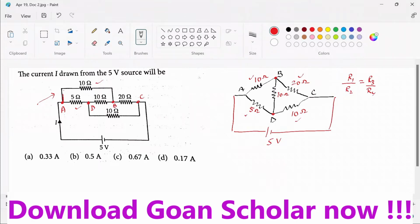And if it happens to be true, what I said in the first problem, if the ratio of R1 is to R2 equals to R3 is to R4, then what we do? We simply remove this middle resistor. Why we remove it? Because this is called the balancing condition of a Wheatstone bridge, that says that if this condition is fulfilled, R1 is to R2 equal to R3 is to R4, then simply there is no current in the middle branch, always. And if it happens, then this 10 ohm and 20 ohm, 5 and 10 ohm, they will be drawn like this.